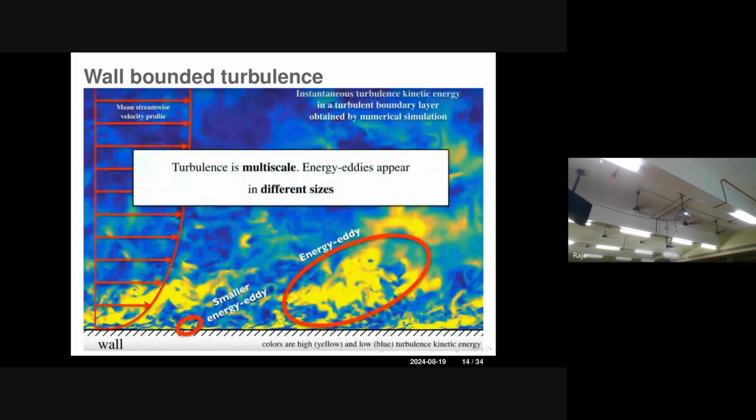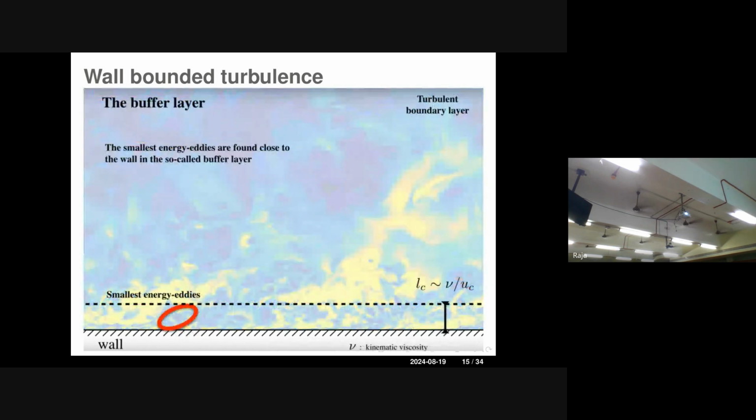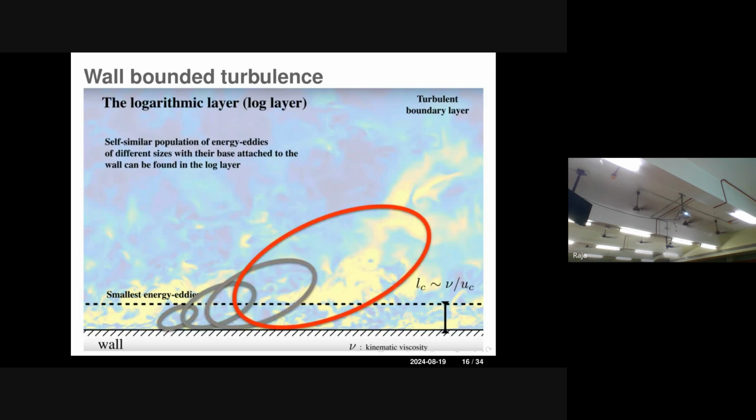The scales may be small but highly energetic, or large but not that energetic. That kind of interaction also happens. They are always multi-scale in nature. If we look at the small scales, they are very focused near the walls where viscous effects are important, so any scaling there is based on viscous quantities.